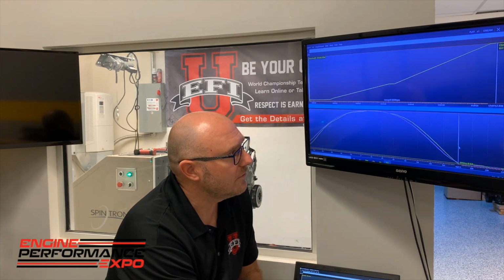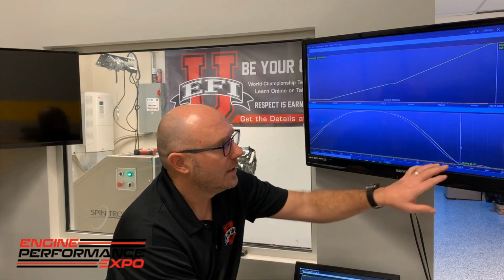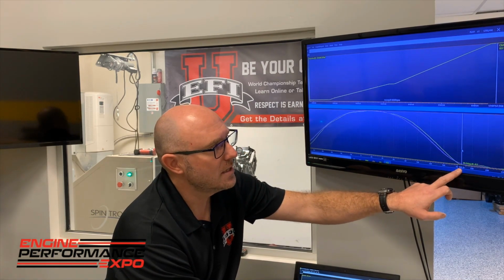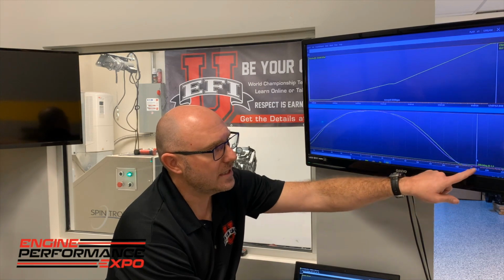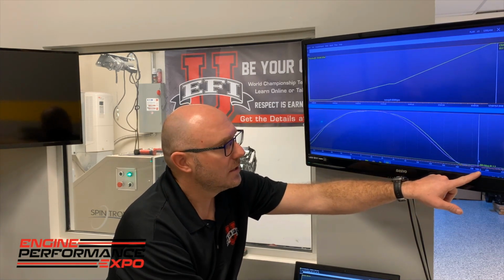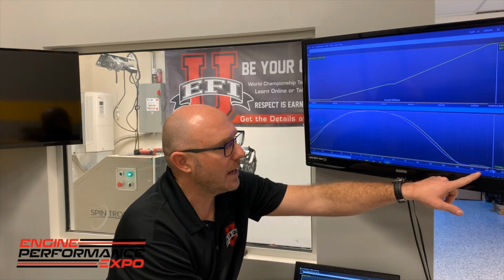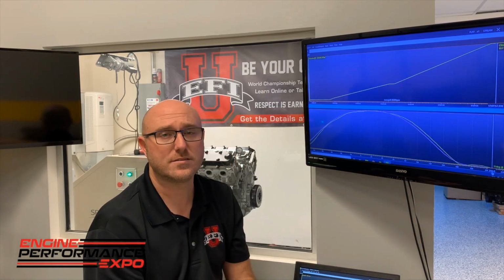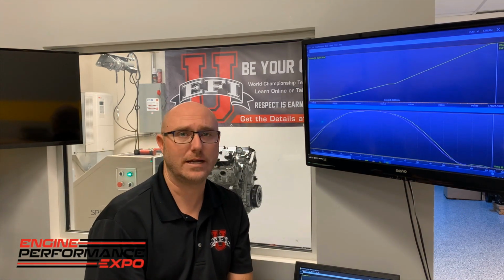So if I zoom in here and look at what's happening, what I can see is that the valve closes here at about, just to keep the math simple, 165 degrees, and then it bounces back off the seat about 13 thousandths of an inch. It doesn't close again until I'm at about, let's just round it off and call it, 205 degrees. That's 40 degrees of duration that the piston was moving and the intake valve wasn't all the way closed.